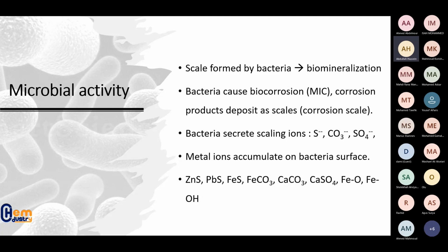It was a mix between methanogens and SRB, and we only found this out when we did the proper analysis for bacterial identification and count. We used PCR, which gave us the exact IDs of the bacteria and the exact counts. Previously, they used the MPN technique, which gave a really low count of the bacteria. It didn't identify all types of bacteria. So you have to be really vigilant whenever you deal with microbial activity. You have to use the proper technique because this can cause really complex and elusive damage.